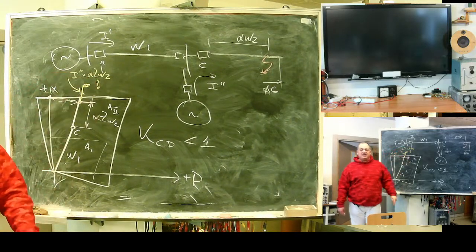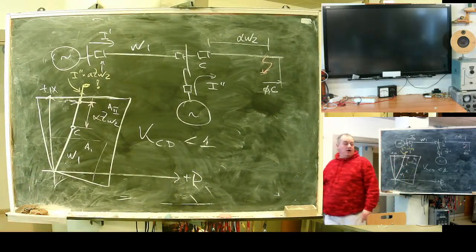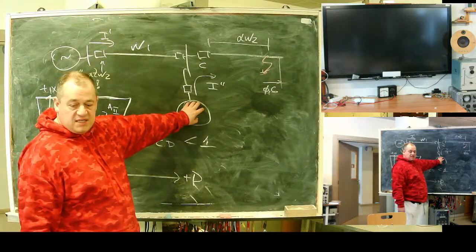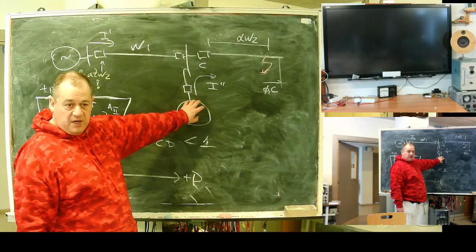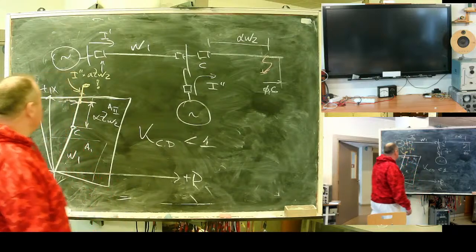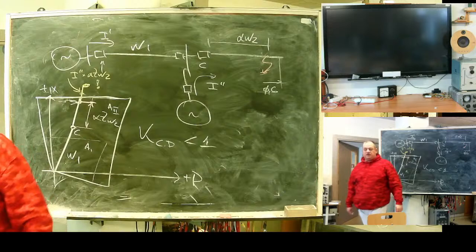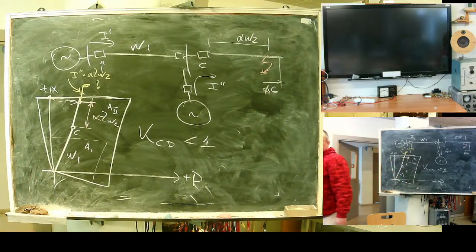It's a very dangerous practice, because in case this generator is unexcited or not operating, if you shift the upper border here, you will get a non-selective trip of your second zone. It's a dangerous thing.